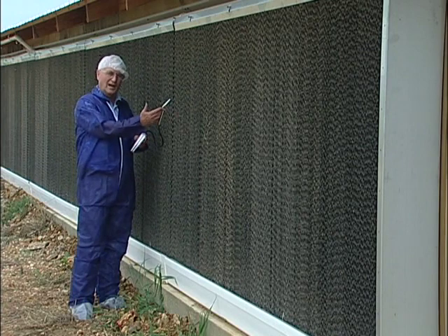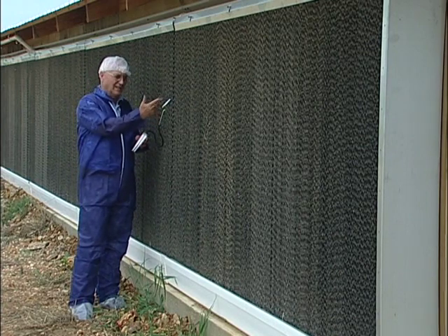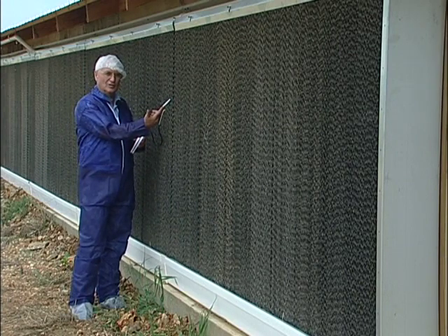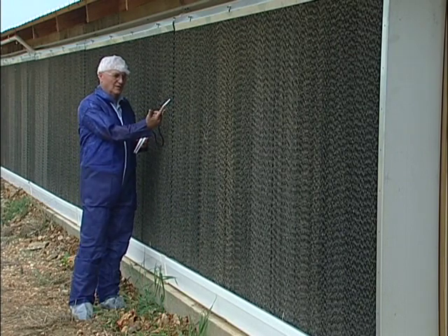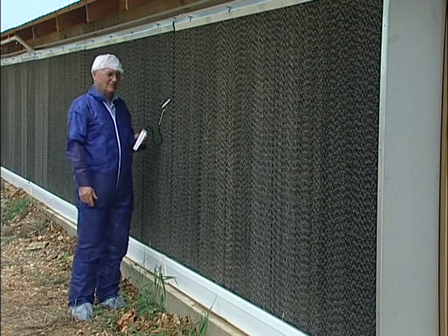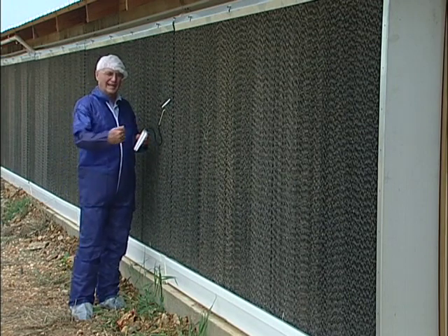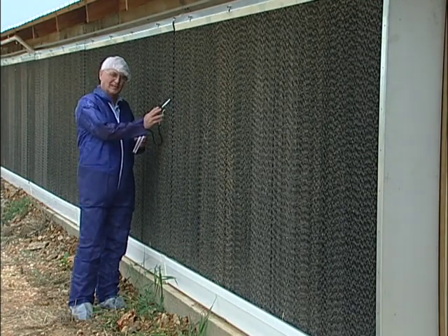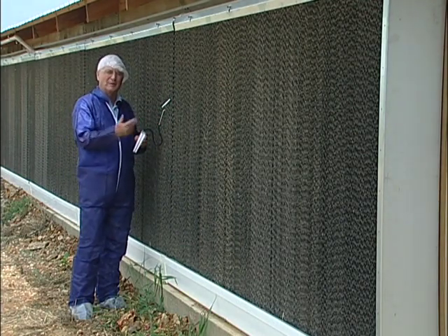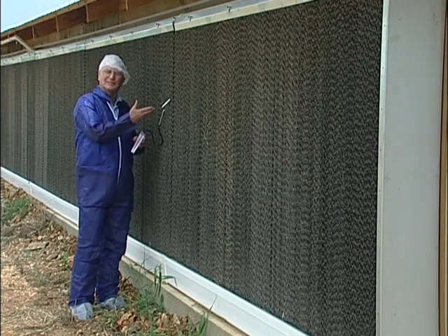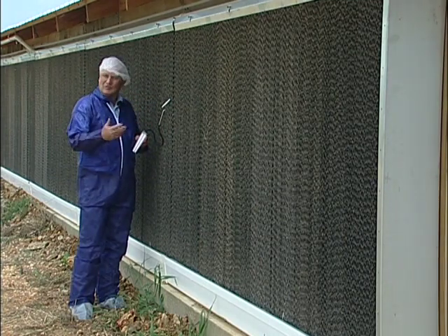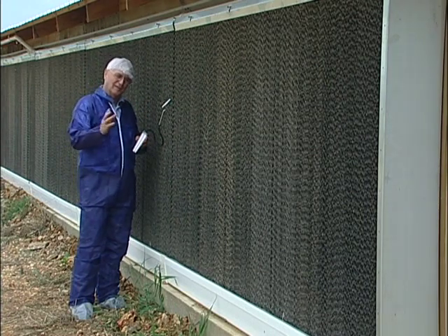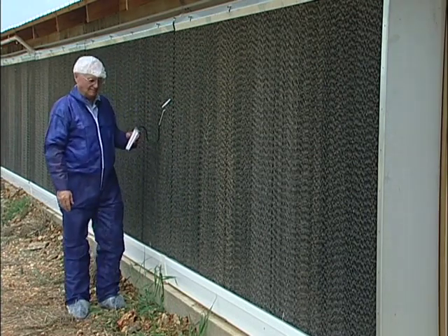And when you put an odd slope pad on the house, like a 45-15, your steeper slope, or your 45-degree angle, has to be to the outside of the house and to the ground. If you got this particular pad in upside down or backwards, you wet your floors inside the house and don't get good cooling. So you have to flow the water against the airflow as it goes through these pads.